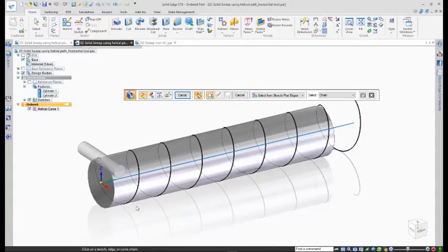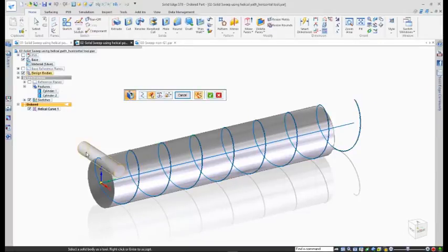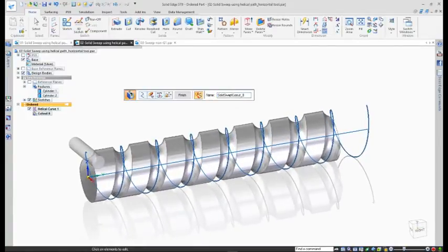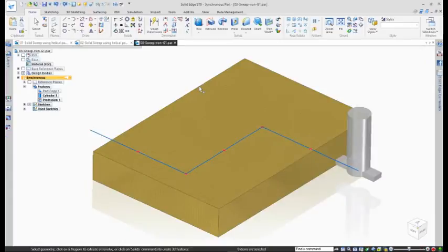Once more, solid sweep, a path, a tool body, an axis, and of course, a reference. Absolutely amazing. What about non-G1 paths? In this case, we have a rotating tool body, and it must travel this path with non-tangent segments. Now how are we going to model that?